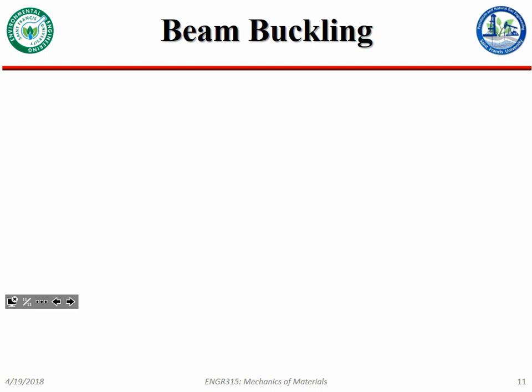From here, we're going to start talking about buckling. And buckling's a really interesting phenomenon. It's still a little bit of a mystery in certain applications, and people are really trying to look at it more. But buckling is the failure of material well before it's failed in yield.